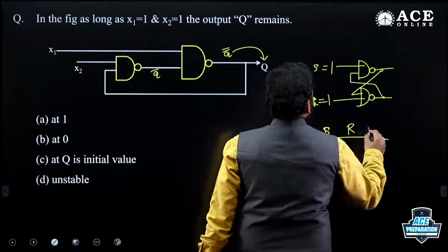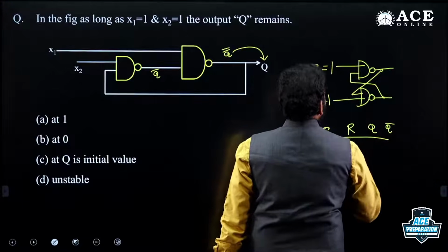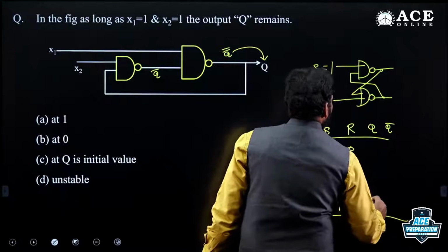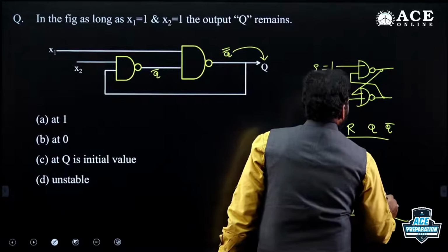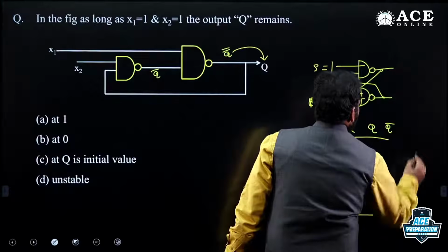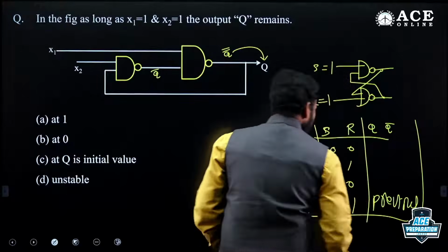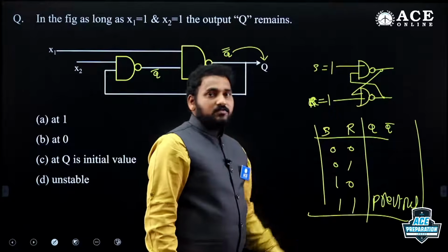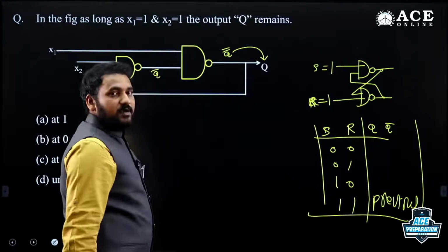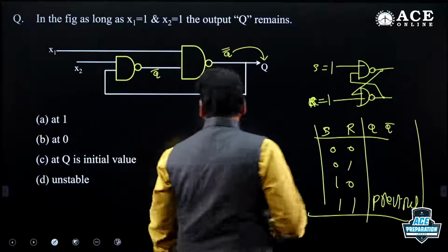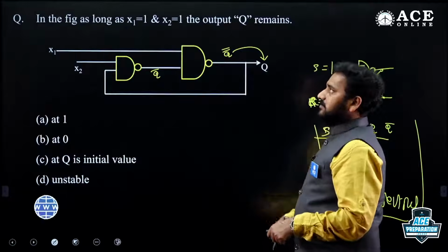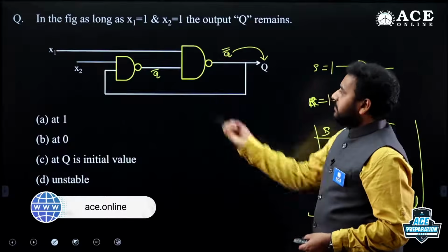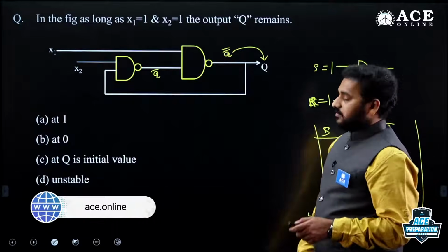The latch, you might have written like this. Q, Q bar output: 0, 0, 0, 1, 1, 0, 1, 1. I am writing the answer for 1, 1. No change or previous state. For the remaining, this is not the topic here. That is the reason I am not writing. This is not allowed state and 1, 0, 0, 1. But both are same. That is what I want to tell you. Even if we fail to recognize the original circuit, we know the fundamentals, you can apply the things and can select the option.